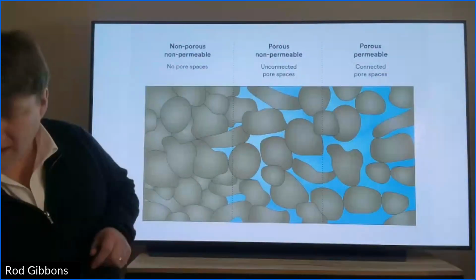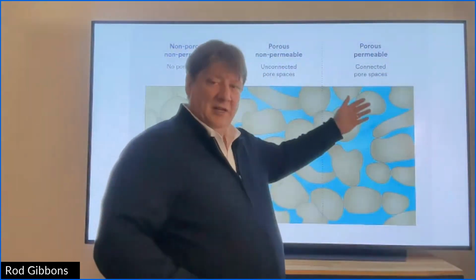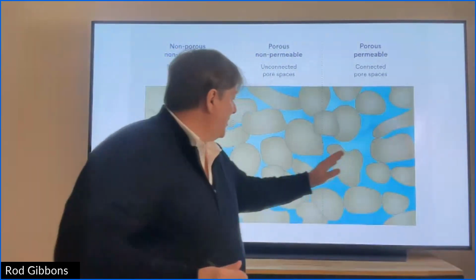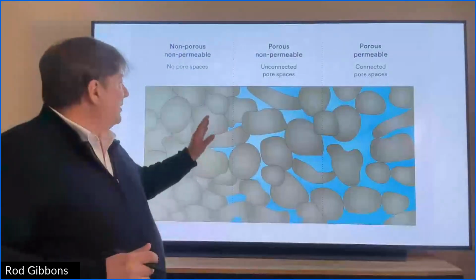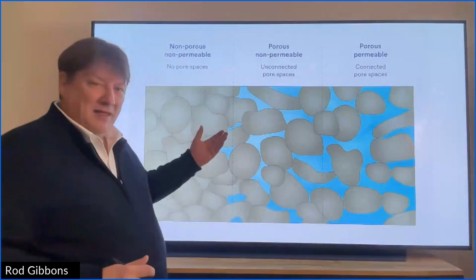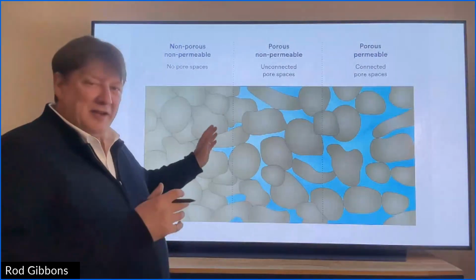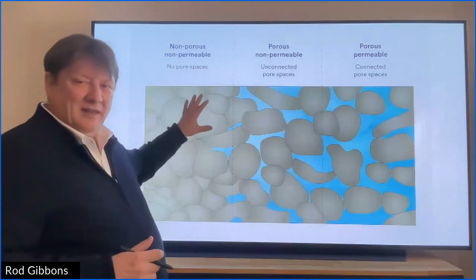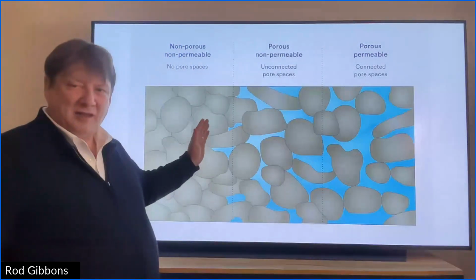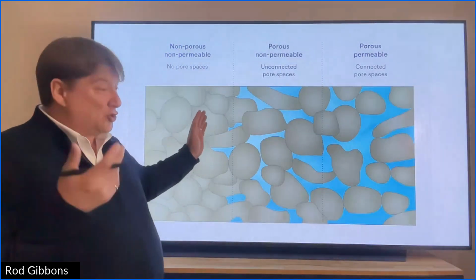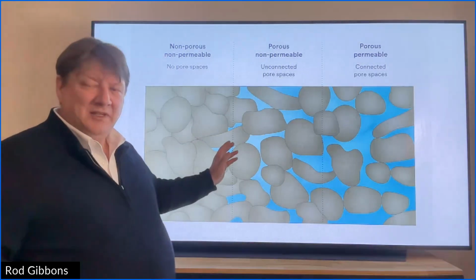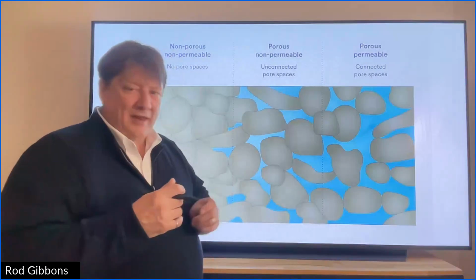If my reservoir looks like this, I've got a really nice reservoir, but right where I drilled my well, I crushed a bunch of that rock, or I put a bunch of chemicals or solids right next to my wellbore. Then I'm getting a good pressure response, but my rate is a lot lower than it should be. This could be formation damage right next to the wellbore.